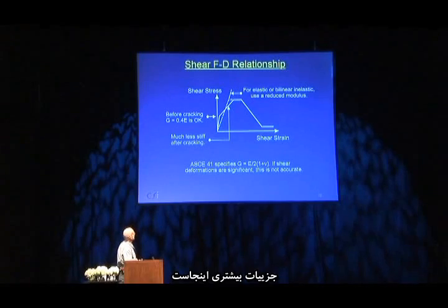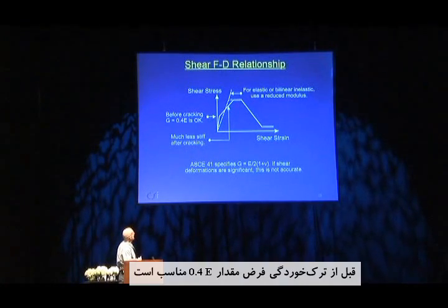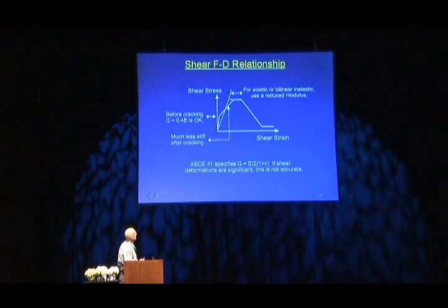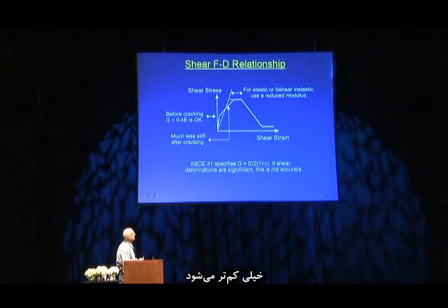I didn't do a very good job there. The important thing here is that a shear stress based on simple formula is not very accurate. This is a little more detail here. Before cracking, it's actually okay to assume G is 0.4E. After that, it's much less.